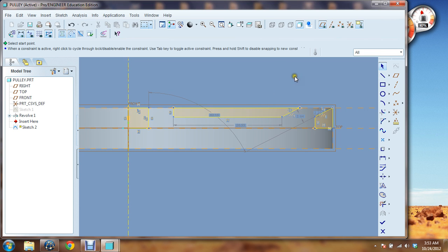thing's closed up. And while we're talking about common mistakes during the workshop, I noticed some of you were laying lines over top of other lines. So if I were to come in here, and I already have this line right here, it's already closed, and I were to make another line on top of this, I would say, okay. Well, now it looks, to me, it looks closed, but it's not.